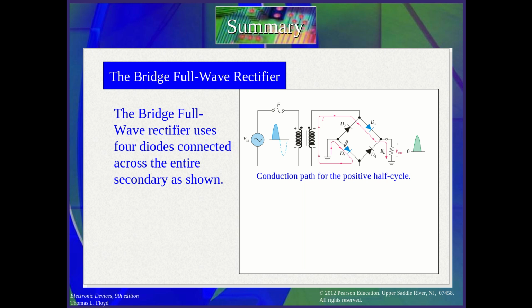Now if you analyze your circuit in the positive half cycle, you will see that the voltage is plus minus, so the current will go through like this. As you see, this is the PN junction, so it will go through the circuit through this diode D1 without any problem. Also, because this is in the circuit, the current will go from here. You see, this is the flow of the current. This one also will conduct.